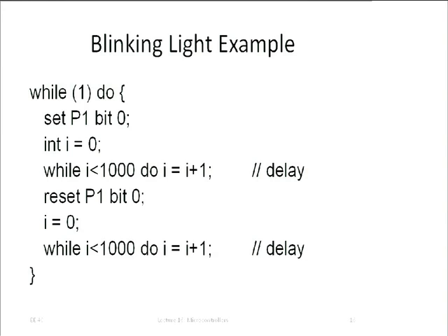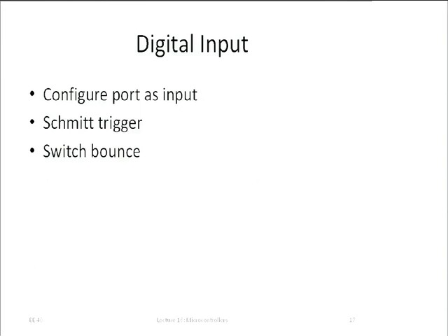Okay, so something similar for digital inputs. Conveniently, digital inputs have something called a Schmitt-Trigger at the front. What is a Schmitt-Trigger? Yeah, it's something that uses positive feedback, and it makes sure that we really determine, is it a 1 or a 0, and we don't flip between 1 and 0, right? So conveniently, these circuits are already built into microcontroller inputs.